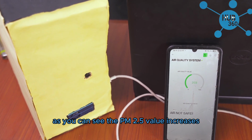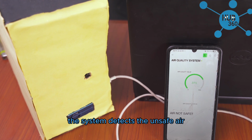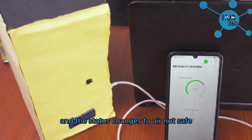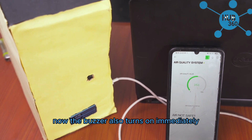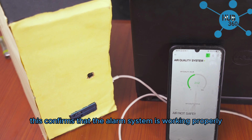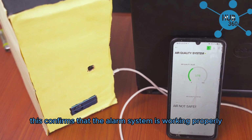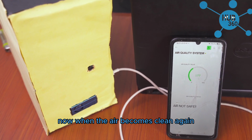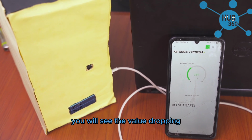As you can see, the PM2.5 value increases. The system detects the unsafe air and the status changes to air not safe. Now, the buzzer also turns on immediately. This confirms that the alert system is working properly. Now, when the air becomes clean again, you will see the value dropping.